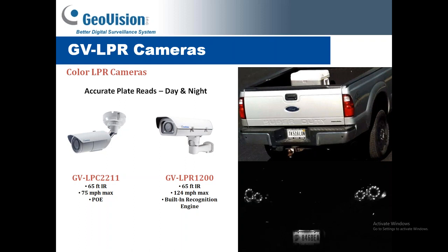And then lastly, license plate recognition. GeoVision is one of the fewer manufacturers in the industry that has true license plate recognition cameras. So these are cameras that are optimized for being able to see a plate both during the day and at night. One thing I will say is that license plate recognition is a trickier topic. These cameras really are meant to focus on like a 1 to 2 car width wide zone. You want to have them mounted and just looking and catching plates. They're not really meant for looking out at a parking lot and trying to catch every plate in a parking lot. The differences between these two, they both have 65 feet of IR range, but the model on the right, the LPR 1200, has a built-in recognition engine in the camera.